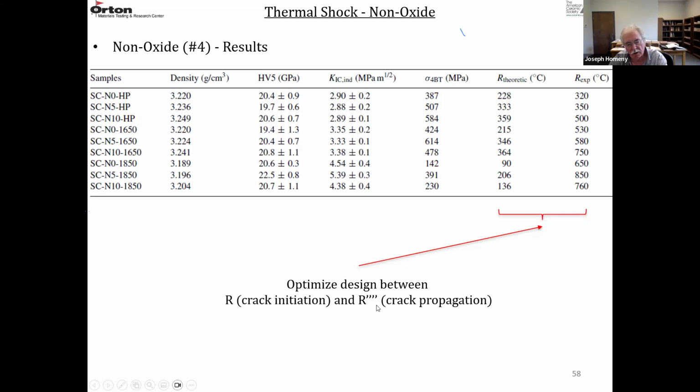So really, perhaps the R4 prime is more applicable in this case than the R value because it's way off here. So you're going in a transition, I think, from a microstructure, fine grain, high performance to a lower strength, more thermal shock resistant structure. So you're probably making a transition from using an R parameter, and you really probably need an R4 parameter in this case here.